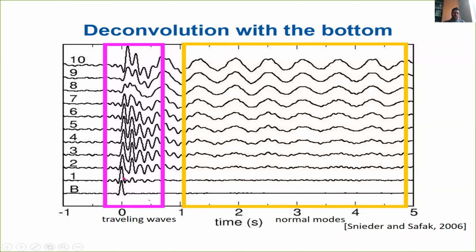The first part is mainly related to the waves traveling up in the building, reaching the top and going down, propagating down in the structure, and then repropagating after having changed the sign of the impulse, because at the bottom, when they find an impedance contrast, which is large, the polarity of the waves changes.